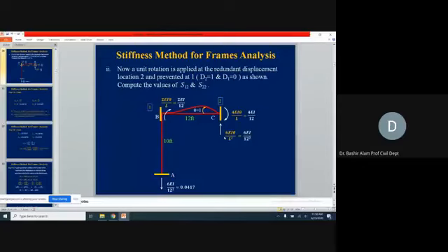And how do we find its direction? It should create a balancing moment to the unbalanced one. The unbalanced one was clockwise, so the balancing one should be counterclockwise. So here this reaction will be in the downward direction, and here it is in the upward direction, and 6EI over 12 square is the magnitude. As we are restraining rotation here only, this 6EI over 12, which is in the downward direction for member BC, for member AB at joint B will become upward. Why?